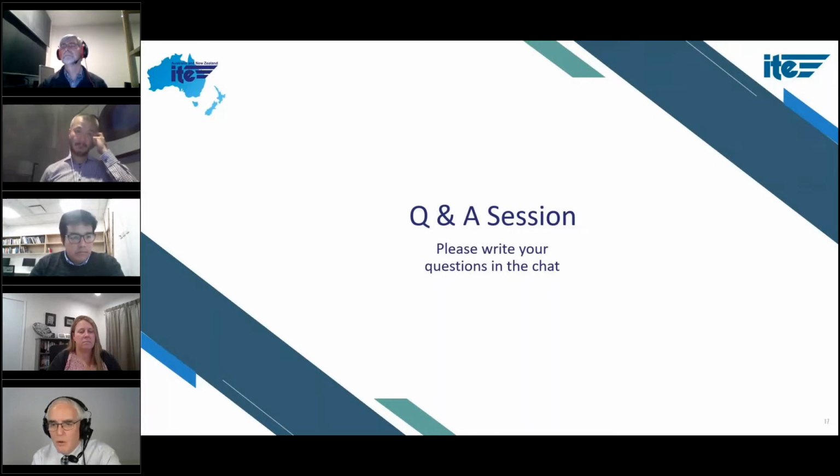Ask us why you are using X as a value. And also, as a general thing about defaults, at least from a SIDRA point of view, there's defaults for everything, but make sure you put in the things you know. Even if you haven't built an intersection yet, you know how wide the lanes are going to be. Don't use the default lane width, and you know what the gradient's going to be. Don't use the default of it being level. So put in everything you can and rely on the defaults for the things you don't know. But I'll open this to others to comment further.